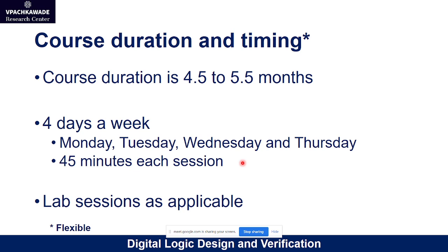Then we'll teach you how to simulate the code and understand the waveforms. We'll also teach you how to understand the generated circuit, because the tool will generate the circuit for you. For example, you designed a counter, wrote the code, simulated it, and the circuit is ready. But you need to understand how that circuit is behaving. That is called verification.